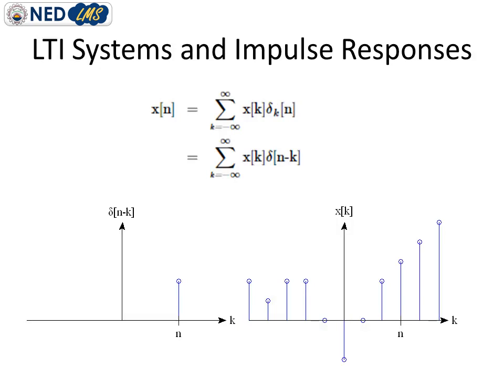So here in the slide we can see that we can represent any signal with the help of impulse signals, and by using the shifting property of impulses, any complicated signal can be decomposed in terms of an infinite sum of shifted and scaled impulses. You can see here the mathematical relationship, and also from the plot that if x of k is your complicated signal, you can formulate or synthesize it with the help of delayed and scaled impulses.